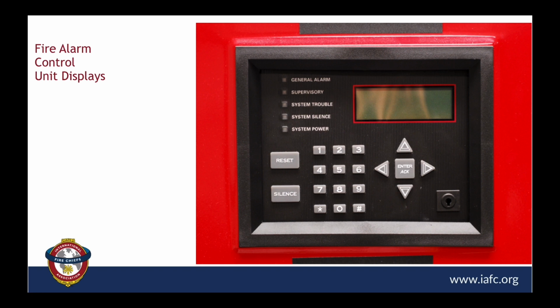I know that some departments, maybe many departments, respond at some level to a trouble condition at the fire alarm system, because this can mean a lot of different things. It could mean that the primary power has been lost and that you're on battery standby, which means your clock is ticking for how long that system will provide life safety to that building's occupants. So that's the trouble light that would light up. The next one down is the system silence light. That lets you know that the alarm has gone off and actions have been taken to silence the system,